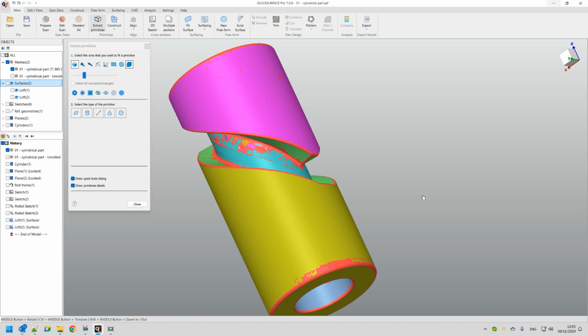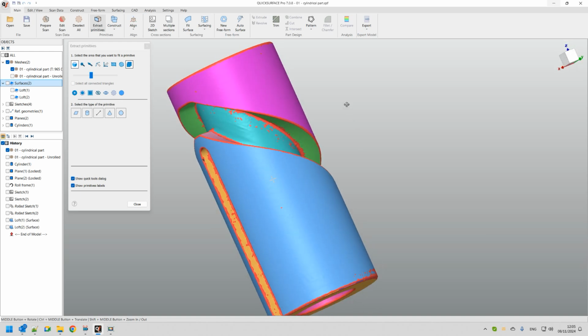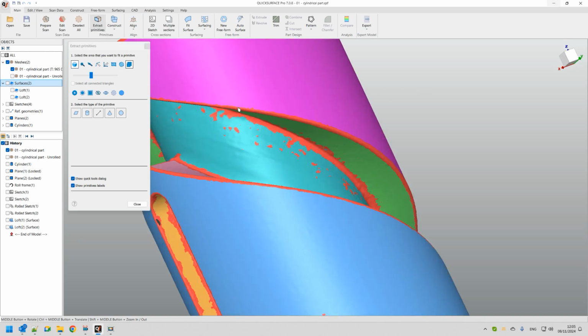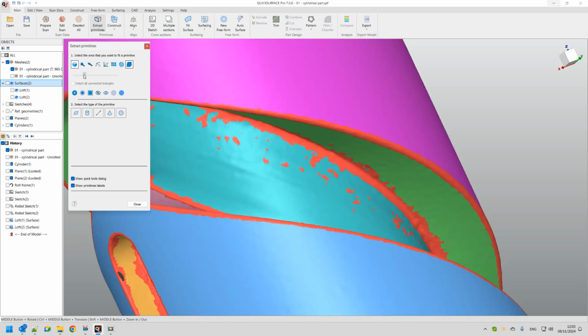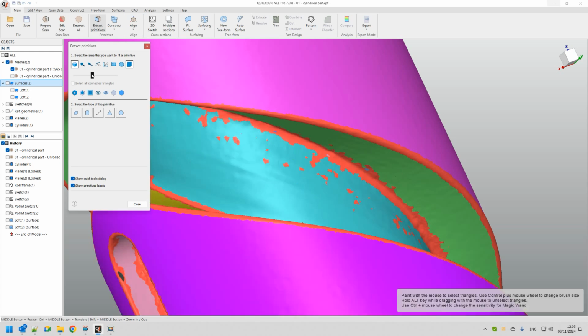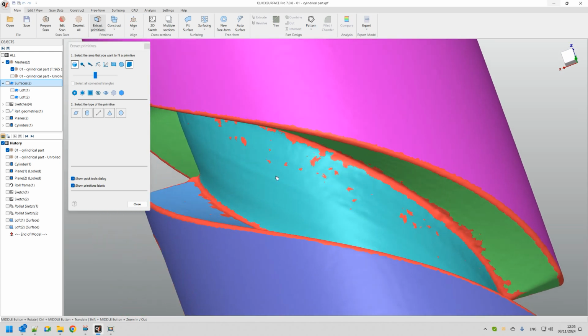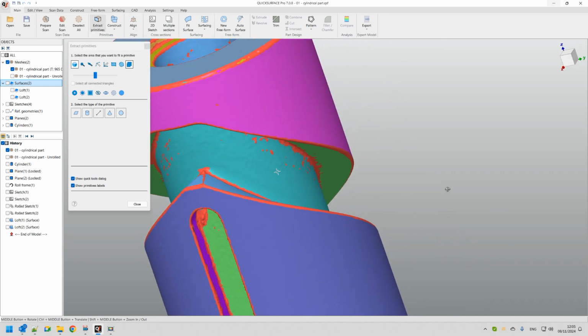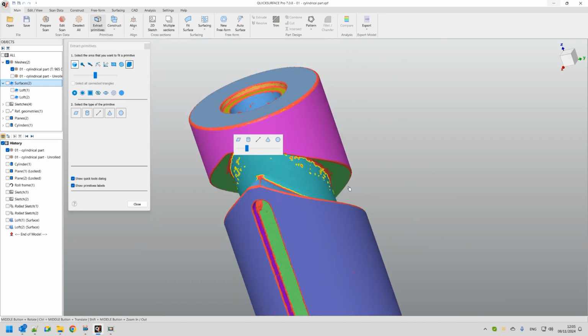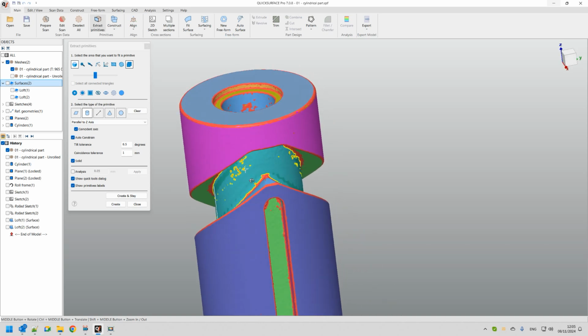The segments are different parts of the mesh that are colorized differently, and they are based on the curvature. You have the control again with the slider to play and see how it has been defined. This is actually to define the radius and the sensitivity of the curvature, so you can pick more accurately. And this is good enough for me. I can just pick on this, and then I can create my cylinder. So this is my extracted cylinder.